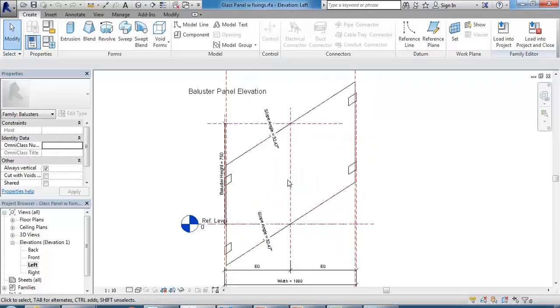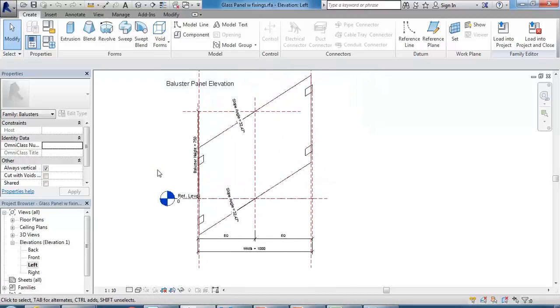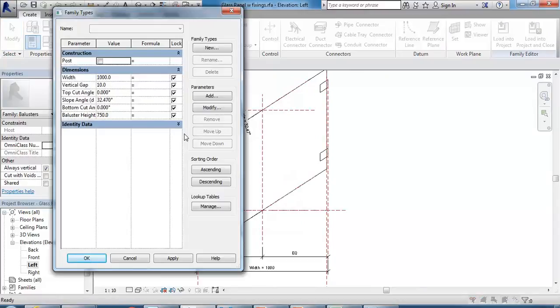And you can see then why it doesn't work too well in the one I've brought it into, because this basically is set up mainly to work with stairs. So it does adjust the angle according to your stair slope, but the width is fixed at 1,000. So if you want that to be adjustable, you need to go and change that width property.